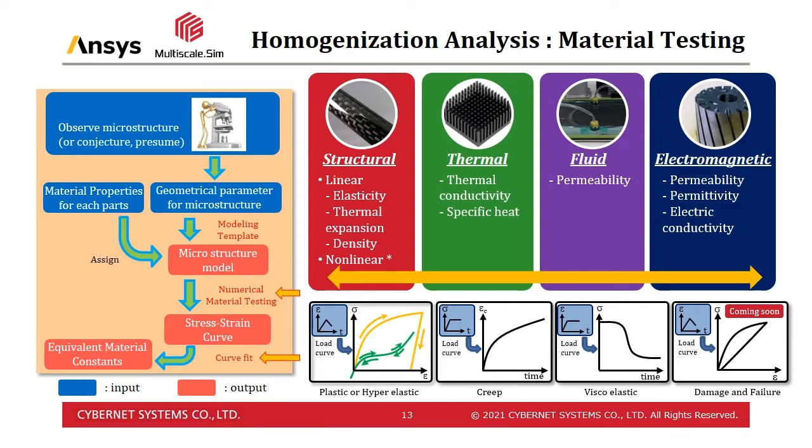These tests can be very expensive in real tests because you have to observe the behavior for a very long time, such as days or years for the creep properties. Virtual material testing has a great advantage in obtaining such properties, which normally takes a long period of time in physical testing. The anisotropic material constitutive law and the curve fitting function for identifying the material constants all are provided by the user subroutine.